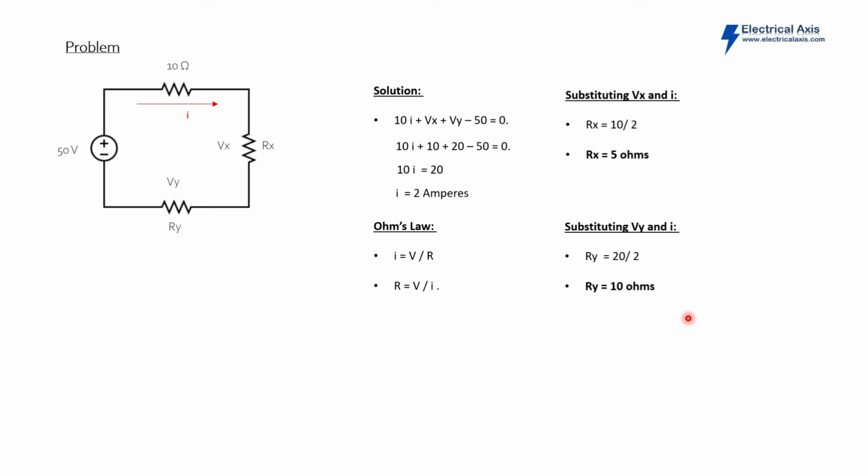Finally, to check whether the obtained values are correct, we can substitute the answers that we get to any equations that we made while we are writing our solution. In this case, we will use the KVL equation that we wrote a while ago.